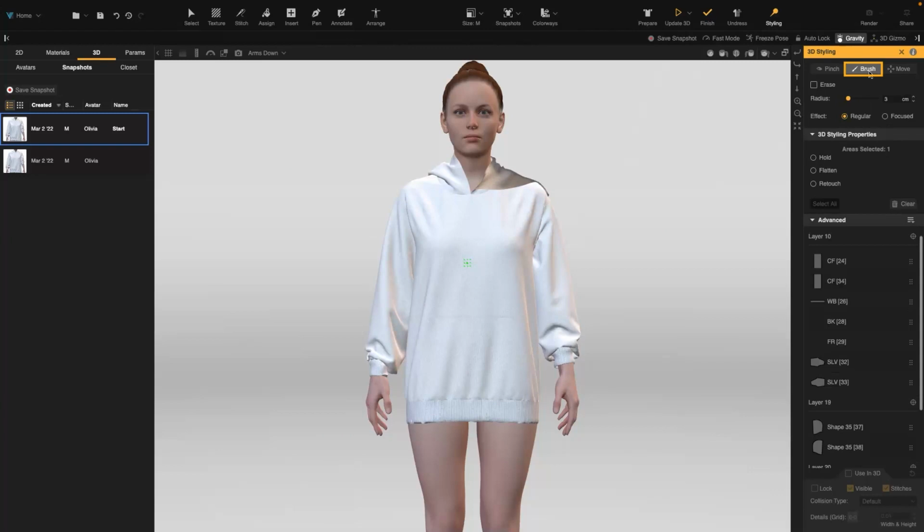When brush is turned on, we can select which areas we would like to move using the brush stroke, then move that selection. To use brush, we left-click and hold our mouse, then move the mouse to make a selection. Once we have selected the area we want, we release the mouse button. Then we hover the mouse over the pin and drag the selected area.